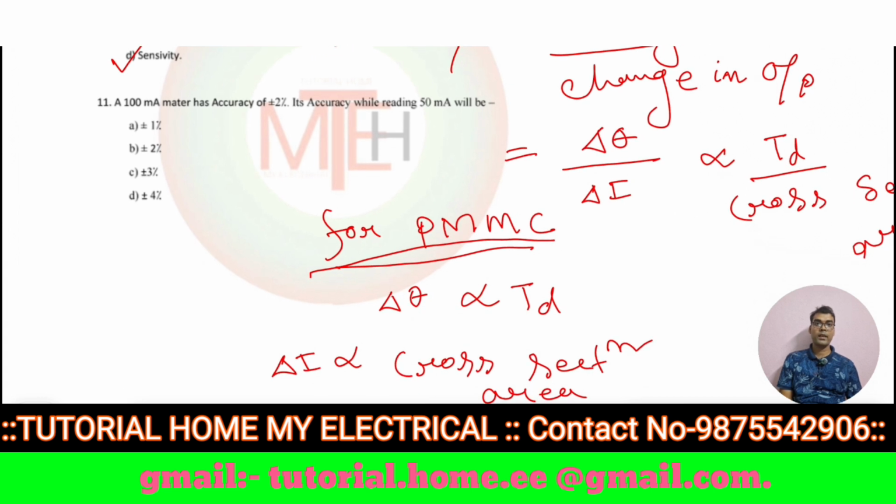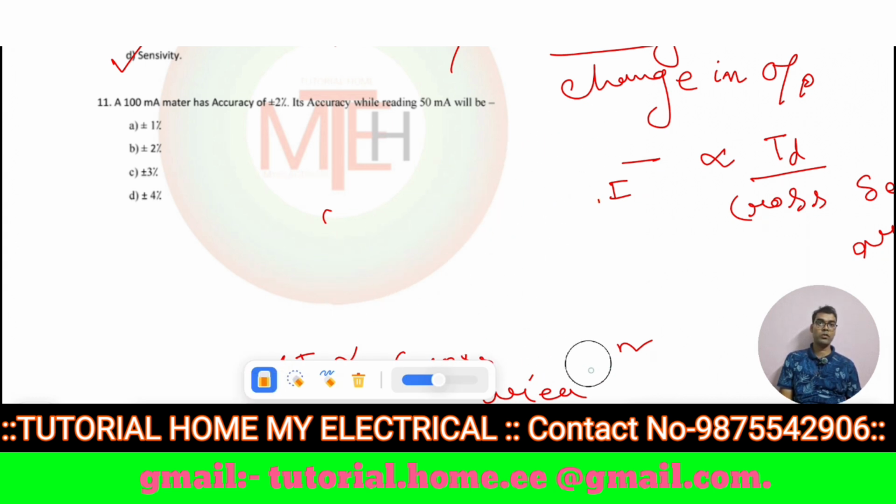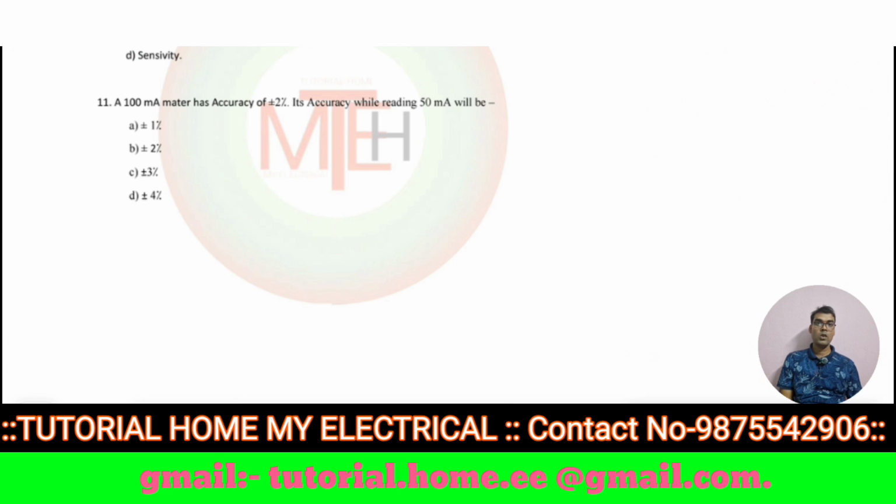In next question, they asked: a 10 milliampere meter has the accuracy of plus minus 2%. Its accuracy while reading 50 milliampere will be. Here we have to understand one situation, that one is accuracy and another is accuracy error.